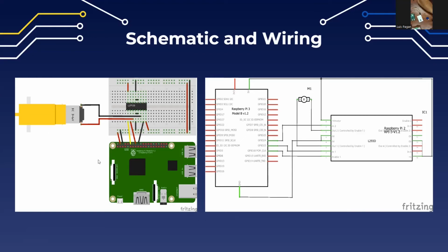So we're gonna pass in 3 controls to this board. 2 of them again are for the direction, so we want to make sure they're the opposite of each other, but they have to either output high or low, and the opposite, obviously, is going to do the opposite. And then we have that signal wire to the enable that's really gonna help us control the speed of the motor.